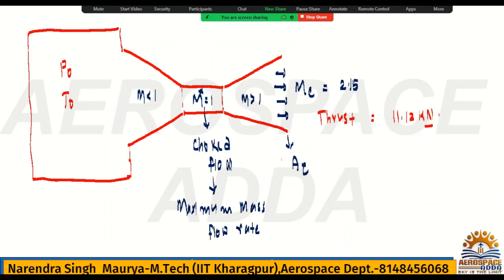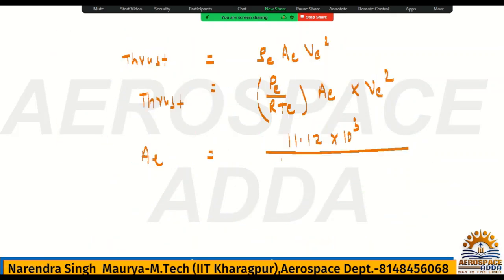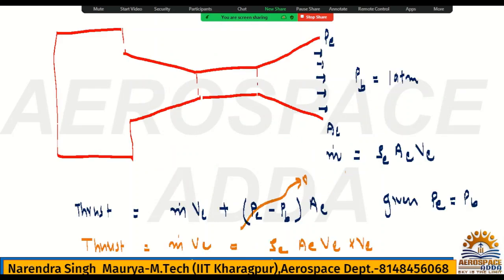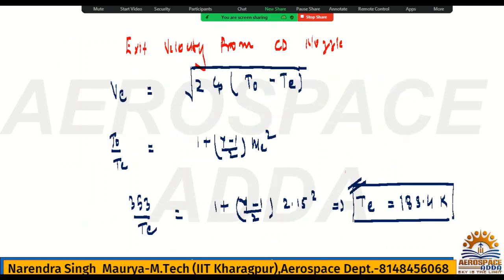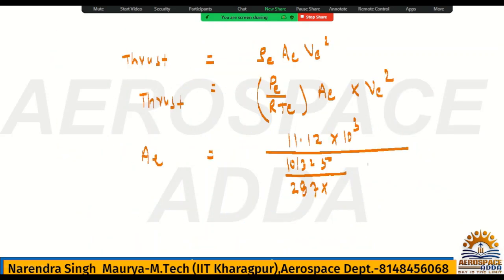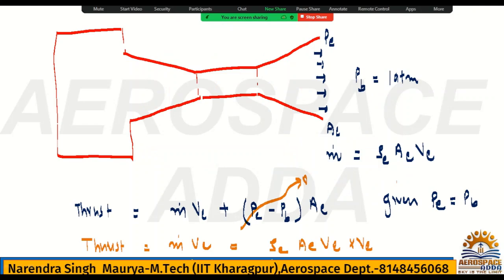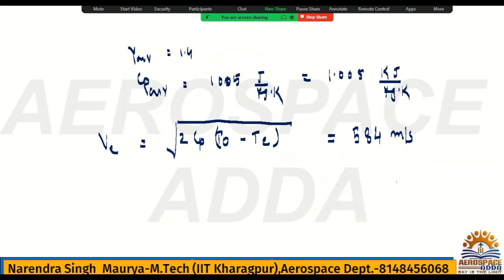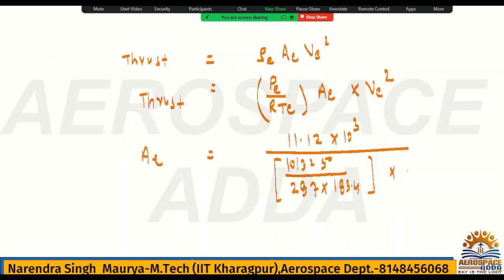PE is PB, 1 atm, which is already given. 1 atmospheric pressure means 101.325, divided by R for air, which is 287, as I told you in previous lectures, times TE, the exit temperature you calculated, 183.4, and VE, the velocity you calculated, 584.